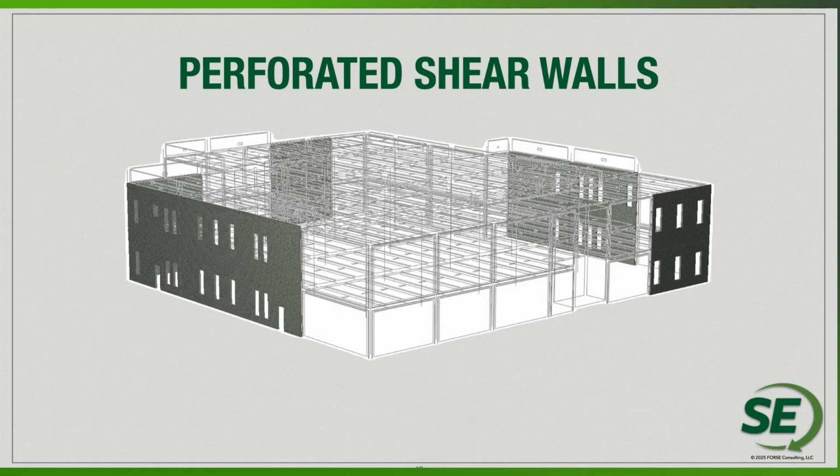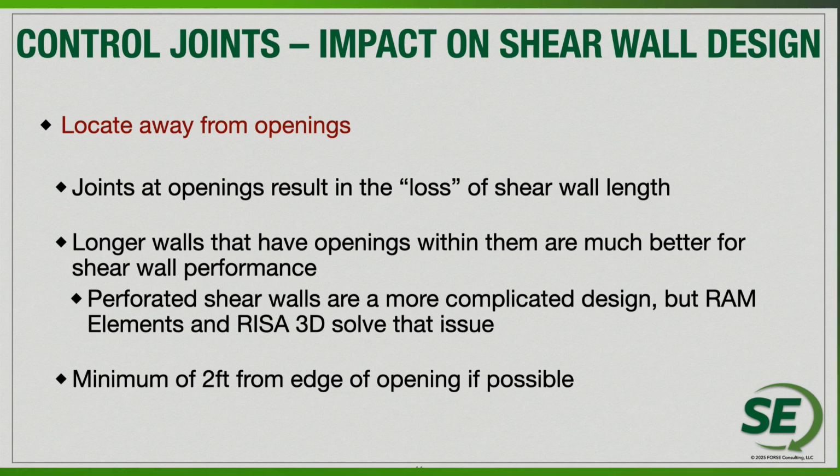Perforated shear walls, again, we have a lot of good architects that are adding openings for their clients, so those openings are going to be within our masonry walls, which is great. But what we utilize today is more perforated shear walls, which is going to allow the overall capacity of the design to go up. It does require a little bit more effort, I think, on the analysis side,